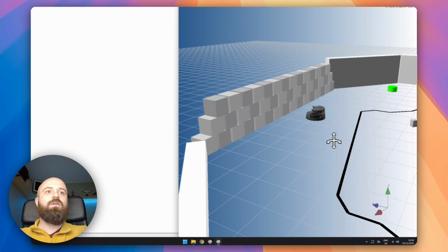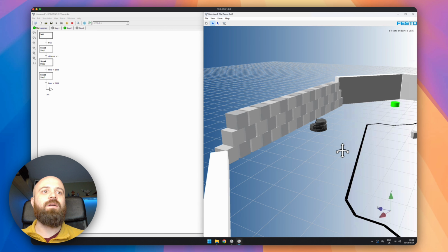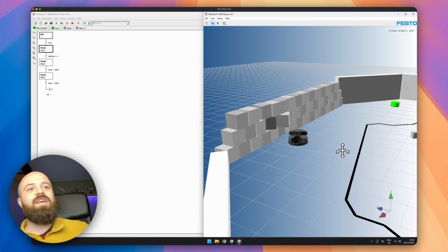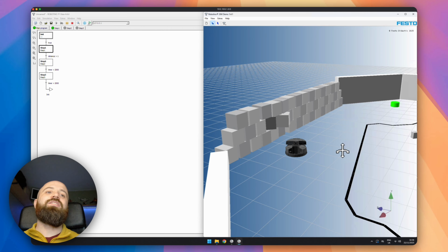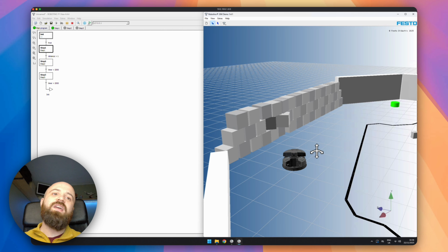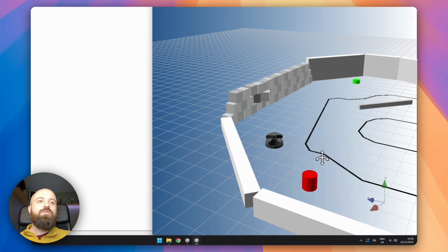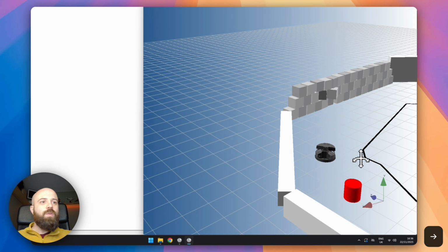So it's getting close, and there we go. Starts driving backwards, turns a bit, and carries on. Is it going to go? Slightly too close. Because I'm only reading the first sensor, it can only detect things that are slightly in front of it. This is obviously something that we should try to fix. But I think we did avoid maybe too much braking on the wall there.